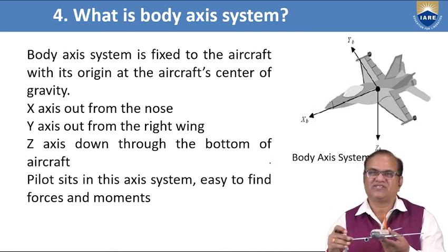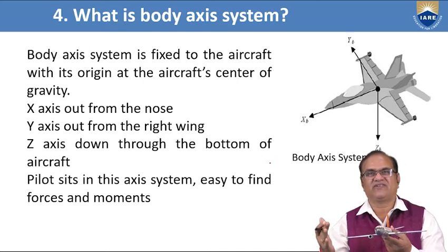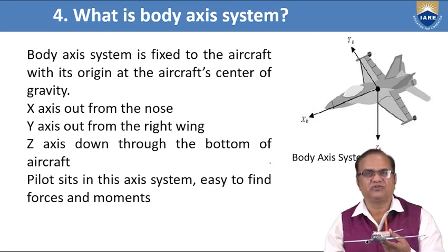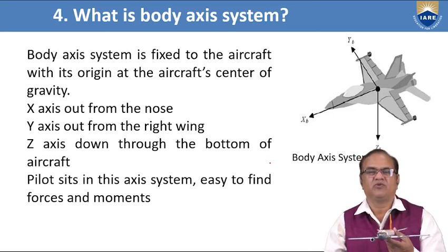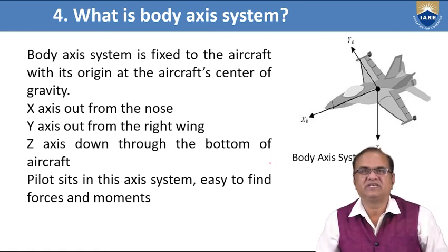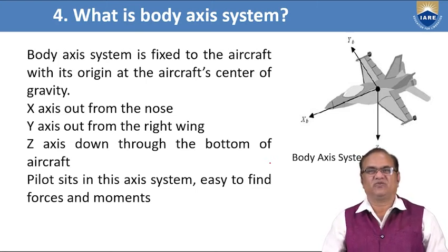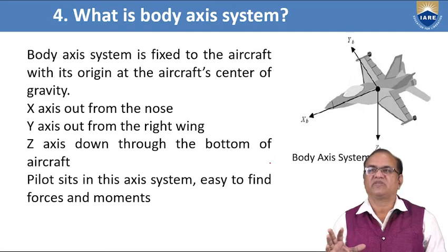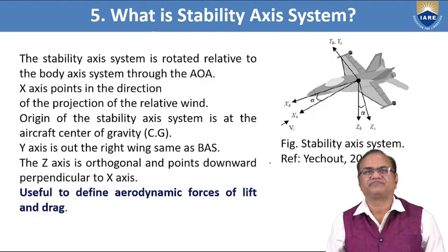So this is the body axis system, and we know that the equations of motion of the aircraft are derived with Newton's law, and just now I have told you that Newton's law and these equations of motion are only applicable in the inertial frame of reference. But the real aircraft is experiencing the body axis system. So we have to convert the derivation, the equations or formulations which we have received, with the help of a transformation from one axis system to another.